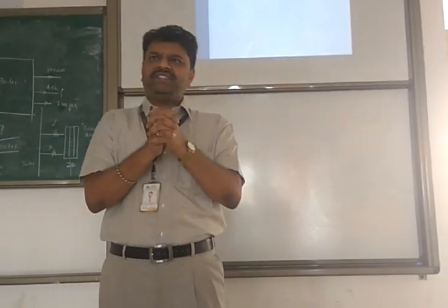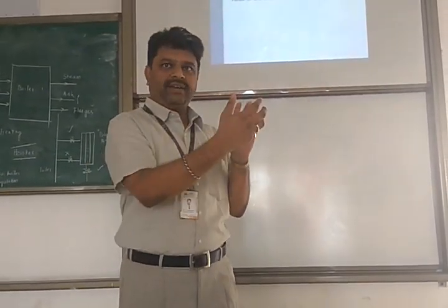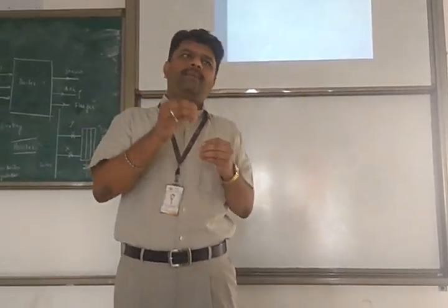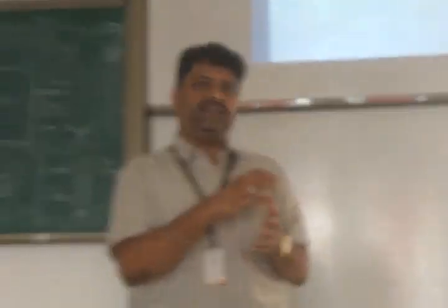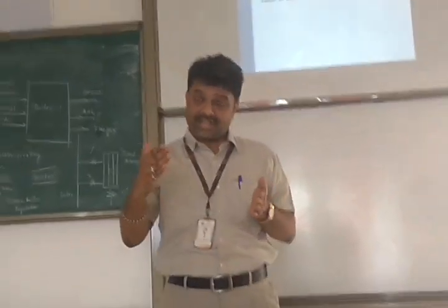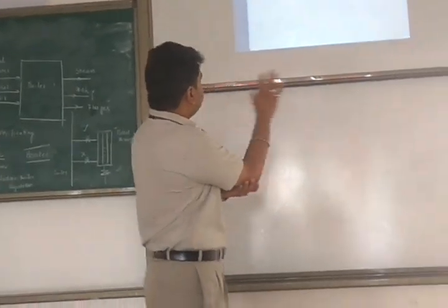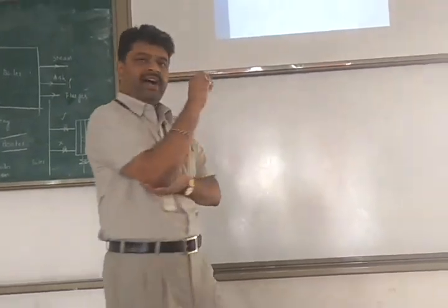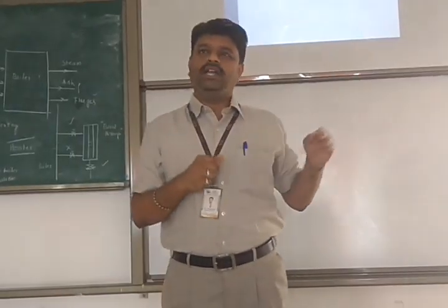So, reference value is for normalizing this value. We have an error, whether it is for 1 degree or for 100 degrees, we should give a number which is applicable for all of this. So they wanted to calculate the percentage of error. Percentage of error is actually a different technical term, I will come to that. Before that, they wanted an accuracy for the entire range. So they divide the error by the reference value, into 100, of course.